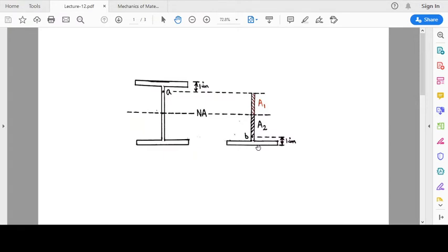The net moment is going to be the same as the moment produced by the portion above point A about the neutral axis. In that way, the two portions will have the same value of Q. So it is always safe to consider the portion in which you do not have the neutral axis.